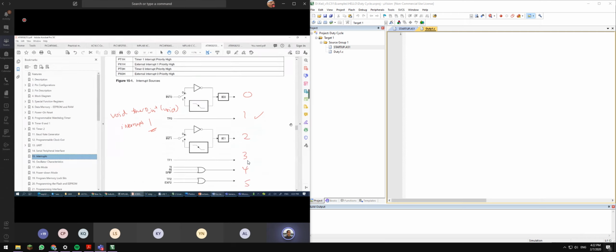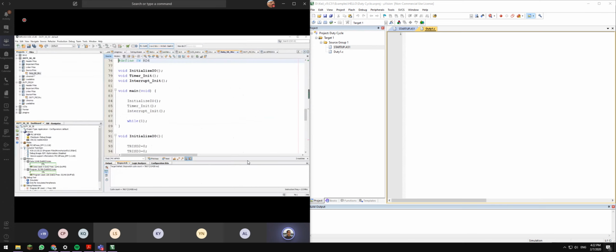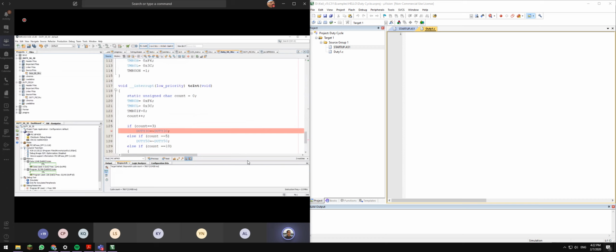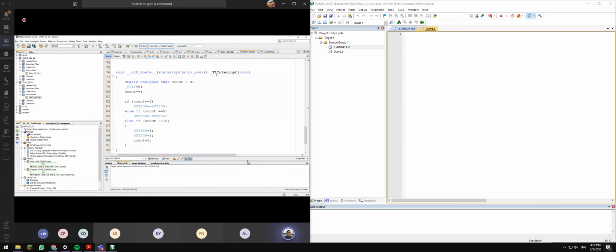And still remember this morning when we wrote our program in PIC 18, let's come back to the program. In PIC 18, the initialization for the interrupt should be like this. Low priority, automatically they know that the timer is already set, whether it's low priority or high priority. When you come to PIC 24, you have to refer to the table. So these are the reserved timer 1, timer 2, timer 0, OC1, OC2, and these are the standards that you should apply.